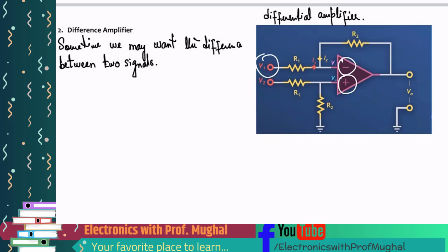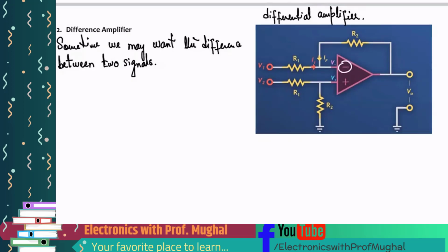So those would be referred to as a differential amplifier, where the two input terminals of the op-amp are connected to an input signal, an AC source. The negative one is the inverting terminal, the positive one is the non-inverting terminal. Now, if you look at the negative terminal here, you have Vout going through a feedback R2. And if you look at the positive terminal, VP, it's not directly connected to the ground. There is a voltage divider configuration at this point, right?